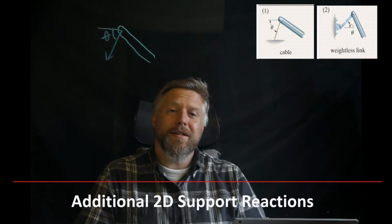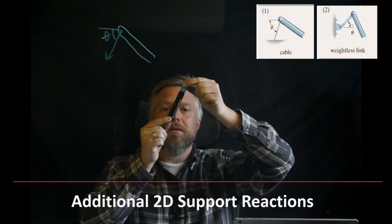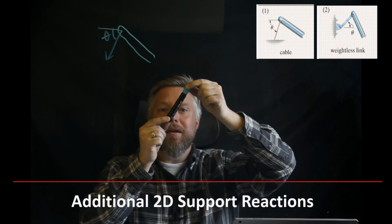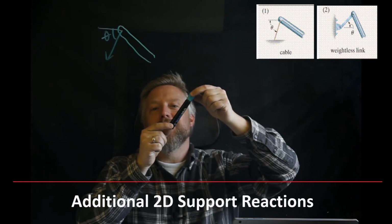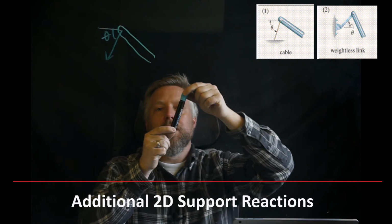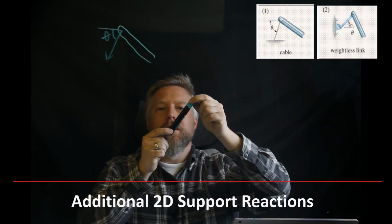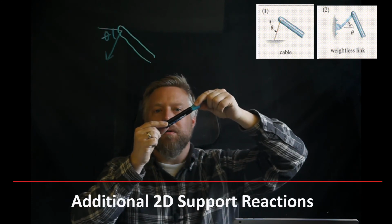Right next to it, you'll see what's called a weightless link. And this is actually a two-force member that you're going to learn a lot about as we continue on rigid body equilibrium. What a two-force member means is it's a member that has pin connections at both ends. Okay, so if you picture this pen having pin connections at both ends, if I were to try to push my hand back and forth, it would just twist. If I were to go down, it just twists. The only way that I can keep it from moving is if I either push or pull.